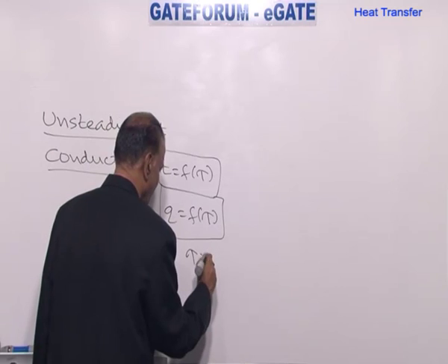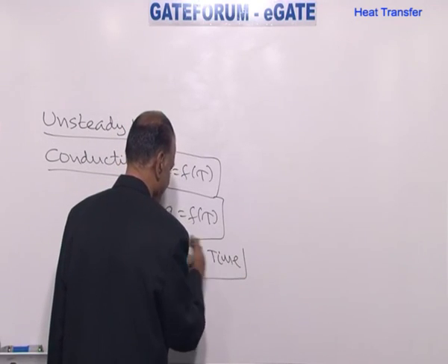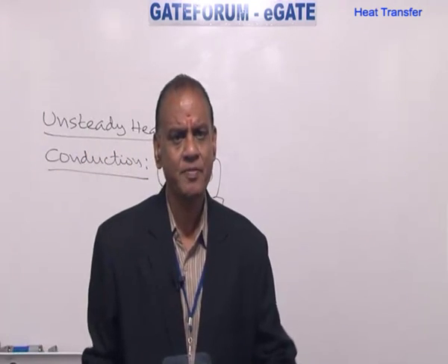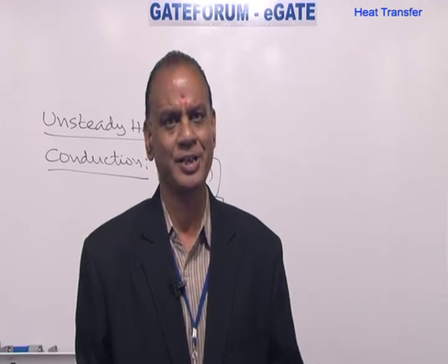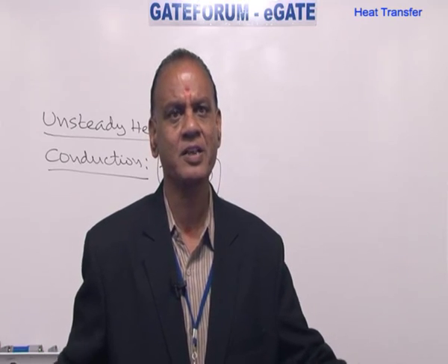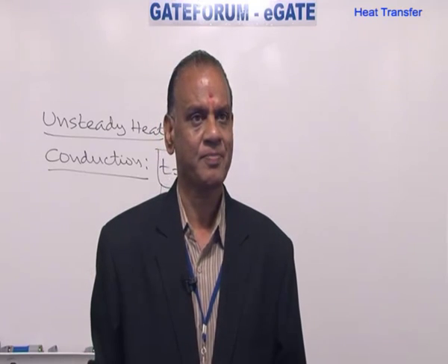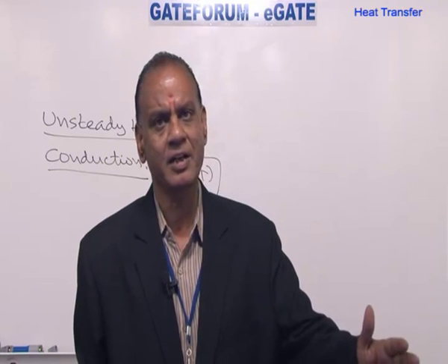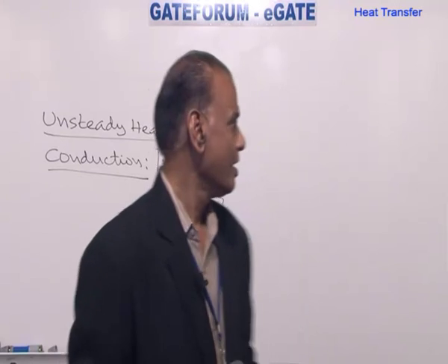You may note that here this Roman letter tau is used to represent the time. Then this unsteadiness prevails in the beginning and near the end of any operation. First 10%, last 5% unsteadiness. In the middle 85% we are going to have steady state heat transfer. Okay? So always unsteadiness prevails near the beginning or near the end of any operation.